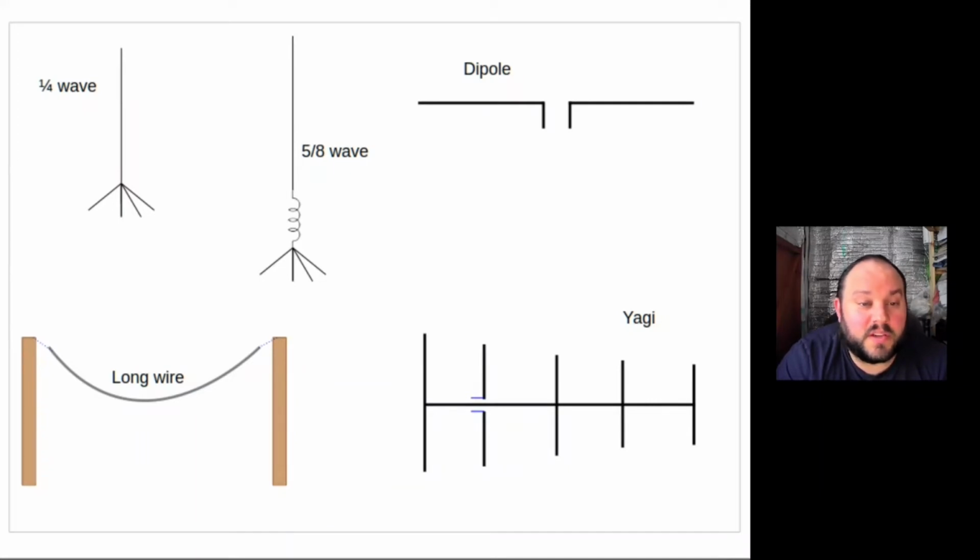The vertically polarised nature of the aerial means that the radio signal is radiated horizontally, which means it's going to be radiated in the best direction to be received by houses and other cars in the area. An improvement on the quarter wave is the 5/8 wave antenna. This has a very similar construction, as you can see, but with a slightly longer length and a coil placed at the bottom. This design improves the strength of the signal going out horizontally when compared with the quarter wave, and it does have a downside, unfortunately, is longer and also less compact.